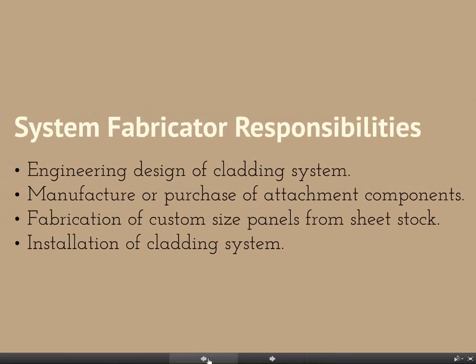Let's talk just a second about the fabrication, and remind folks that the four sides have to be folded. So if you have a curved panel, you have to make cuts in those edges and make other special arrangements to do curves. In some cases, like a cutout, we designed a building 3 years ago that had some glazing that had a curved jamb, and it was in ACM, and they actually had to cut a separate piece of ACM. Once they cut the curve in the flat sheet, then they cut a little strip, bent it to the right shape, and glued it in place with epoxy, and then had angles to reinforce that joint.